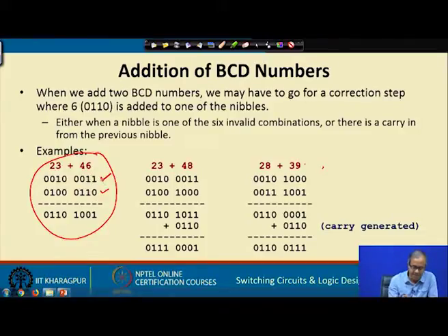Now, when you add, bit by bit we follow the same rule for binary addition. 1 plus 0 is 1, no carry, 1 and 1 is 0 with a carry of 1, 1 and 1 is 0 with a carry of 1, 1 0 0 is 1, no carry, all 0, 0 1 is 1, no carry, 0 is 0.